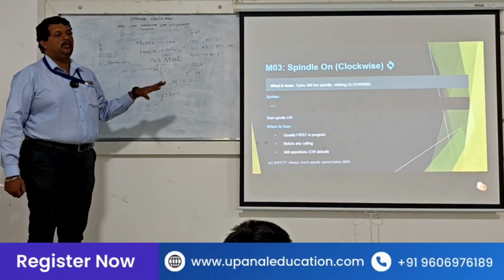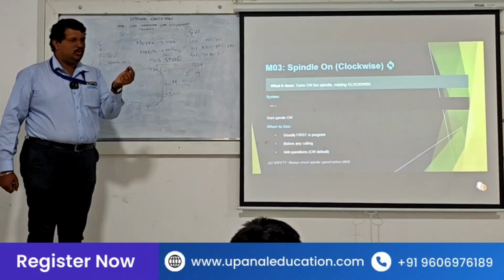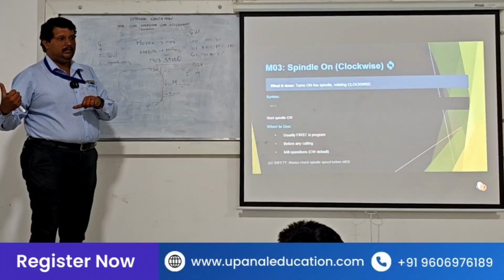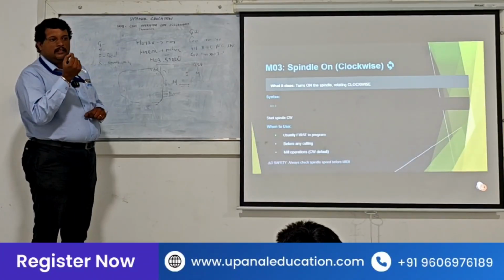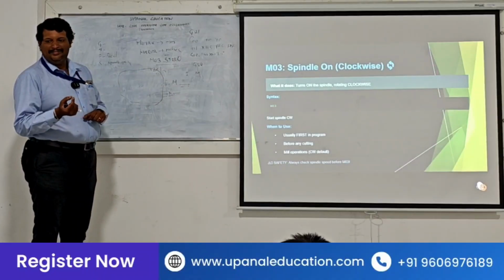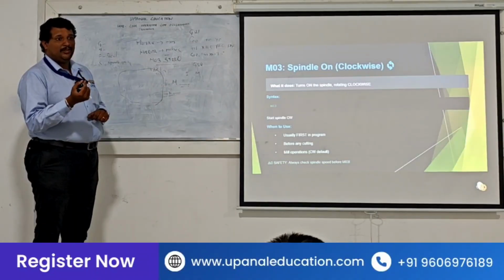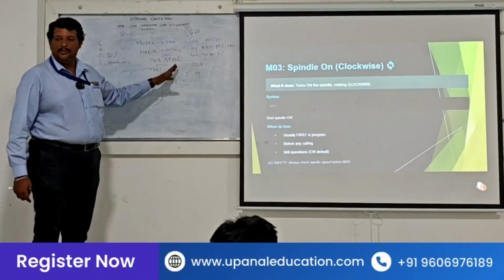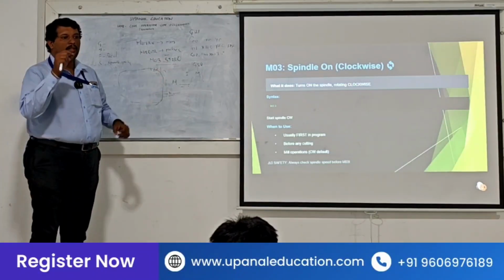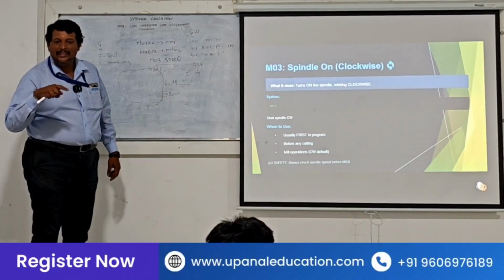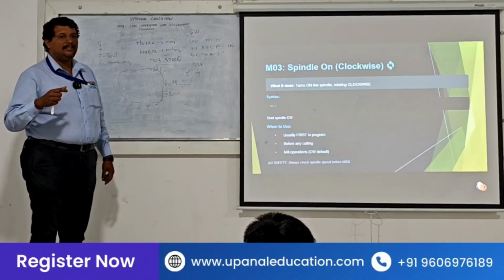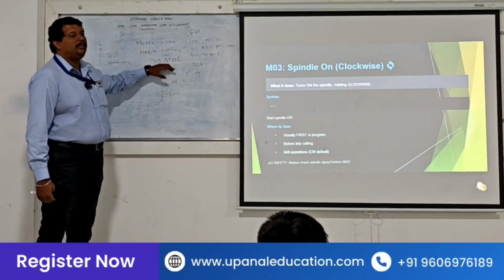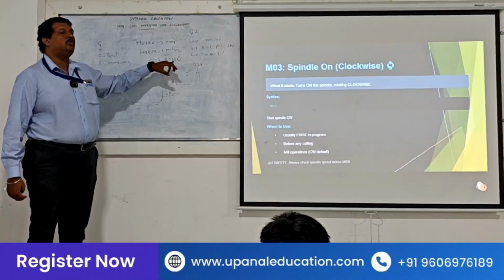It depends on the machine and tool. We used to use small tools. In my previous company we had an old machine, and there we used cutters of 0.5 mm. There we would give M03 S maybe 48,000 or 1 lakh, because the smaller the cutter, the higher the speed, and the larger the cutter, the smaller the speed. So this S5000 may change. We may even run 1,000.